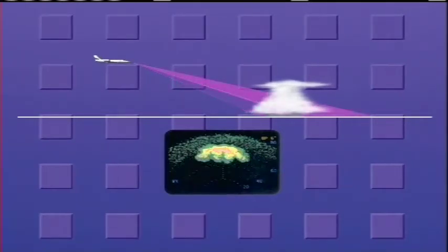One of the most difficult tasks when using airborne weather radar is separating weather targets from ground targets. This is especially true since the maximum return from a storm cell occurs when the radiation beam is centered on the rainfall shaft. In many cases, this shaft may be no higher than 5,000 feet, thus requiring some antenna down tilt to observe it. If you are flying at an altitude considerably above this, the antenna beam will also strike the ground, masking the storm cells with ground targets. In these situations, the proper adjustment of the antenna tilt will help you achieve optimum target identification.